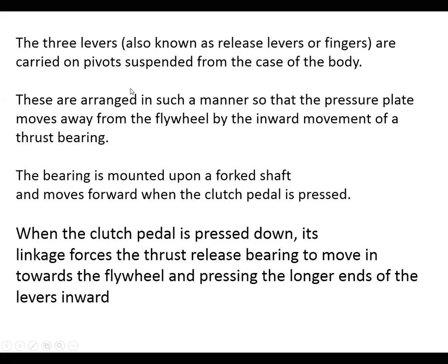Next, three levers are carried, pivoted and suspended from the case of the body. This arrangement is such that the pressure plate moves away from the flywheel by the inward movement of the thrust bearing. So these are the two concepts here: the engaging position and the disengaging position.